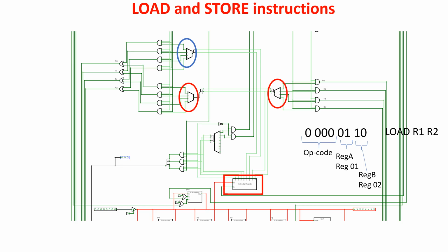The decoder selects the right register, but the right time for the pulses comes from the clock enable and clock set along with the proper step. Here comes the step for the enable of reg B, the step for the enable of reg A, and eventually the step for the set of reg B, which is the last step, in which we store the result of the ALU operation in a register.